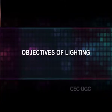When a surface of 1 square foot is placed at a distance of 1 foot from a candle, it offers 1 foot candle illumination on that surface. When the surface is 4 square feet and placed at a distance of 2 feet from the candle, the same amount of light is thinly spread over a wider area and the illumination will be thin, less than in the first case. Similarly, when a surface of 9 square feet is placed at a distance of 3 feet, the illumination will be still thinner than in the second case.